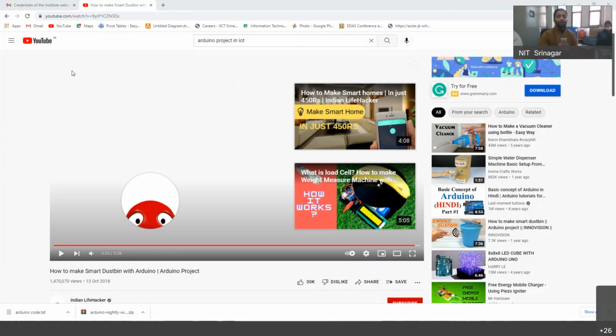Over here, you can find all these things on the internet as well. These are all sorts of programming code for most of the sensors and the connectivity modules, whether it is Bluetooth, Wi-Fi, wireless LAN, or Zigbee. Most of those code modules or packages are already available in Arduino, or you can get all those codes from Google. The main setting that you require here is to select which board you are using. Right now I am using the Arduino Uno board, so you need to select Arduino Uno.